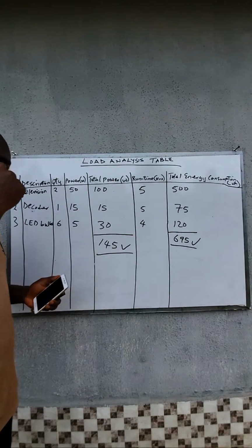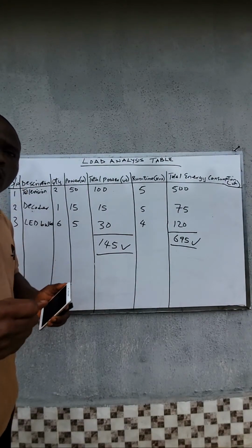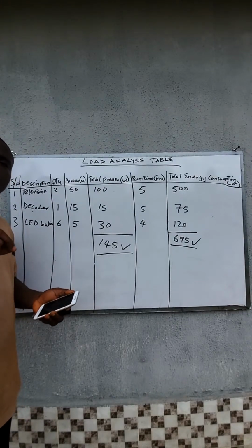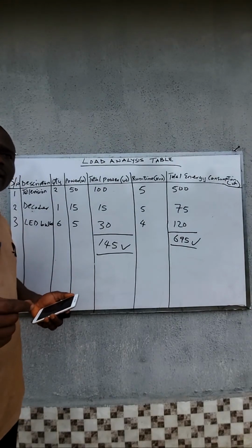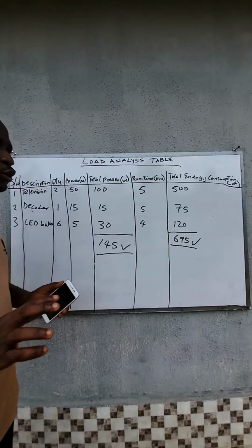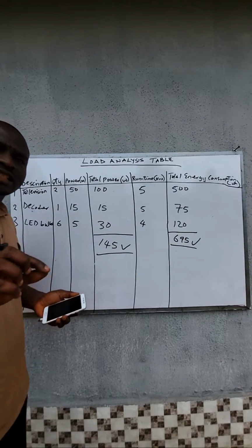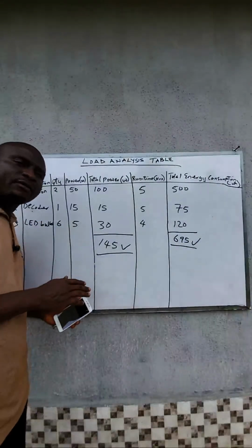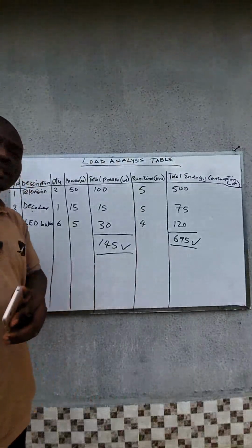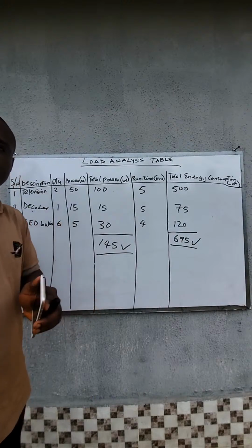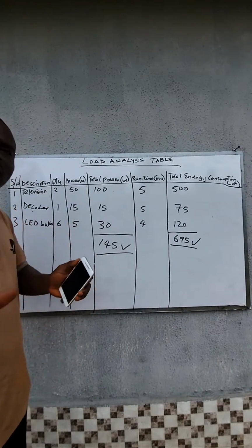Anytime you're charging or discharging the batteries and it becomes too hot, it means there's a problem in that battery bank. It's not good for the temperature of a battery to be high. It is not good for your battery bank. So always look at that charger if it can handle the charging of your deep cycle batteries. Remember, car batteries are different from deep cycle batteries. That is why we don't use car batteries for solar installations. We only use deep cycle batteries.